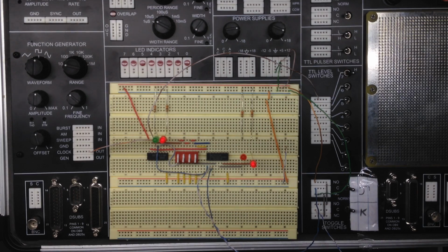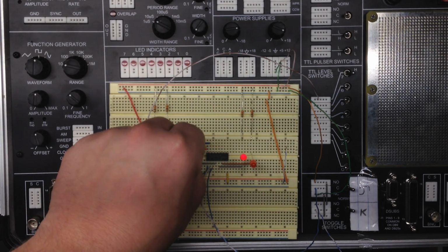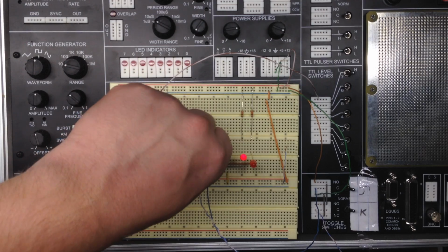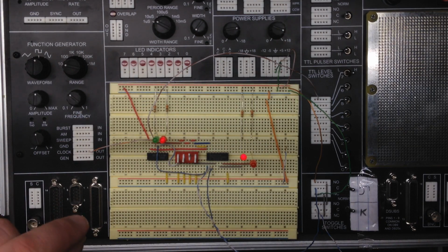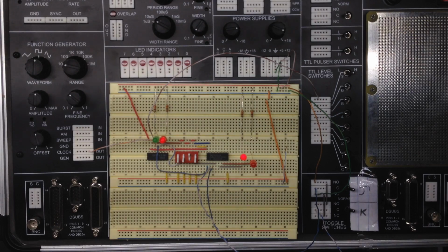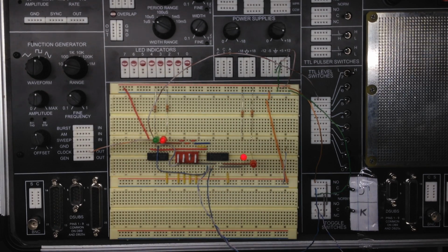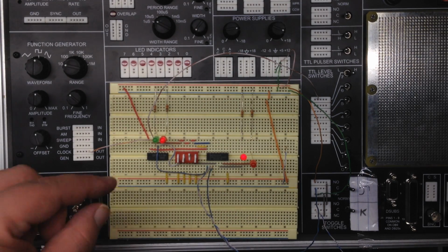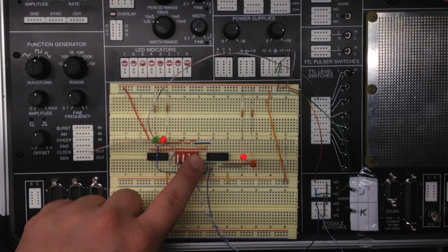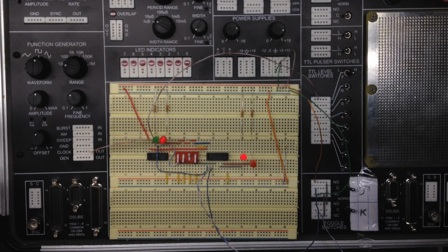And then if we change the state of clear so that it is low with preset being high, we're looking for a low on Q and a high on Q naught, and we see that we have that respectively. The last portion of working with lows on the preset and the clear is reaching a point of having low on preset and clear. Similar to how the D series flip-flop worked, this is another one of those unstable operations, one that is not intended to be used. So anytime that you're dealing with this, we shouldn't have this happen because we can't really guarantee a specific outcome.